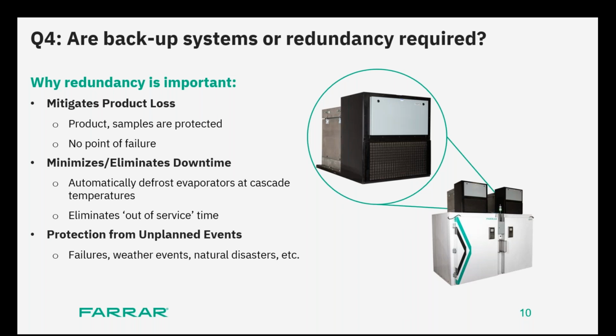So we'll call, let's say, the first system side A, and we'll call the second system side B. So let's say you have side A up and running, say every 12 hours or 24 hours, you'll do a switchover to side B. And then side B will run 12 hours or 24. Many people prefer to do it at the 24-hour time interval because that's usually a first shift at a plant, and there's more people, more activities, and a lot of coverage in that area during those times.